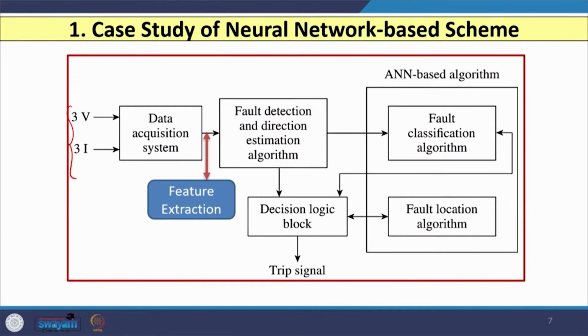featured also, that means feature extraction can also be carried out, because whatever data we acquire, let us say we acquire 3 voltages and 3 currents, then we do not require all 3 voltages and 3 currents, we require only specific data, let us say 3 currents or maybe sequence components of voltage or currents or any other rate of change of sequence component or rate of change of voltage component. So, feature extraction plays an important role to capture only the useful features based on which the classification can be